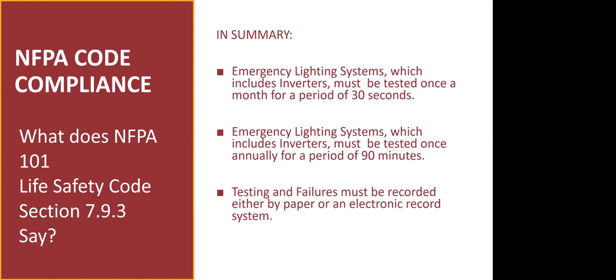That is the following. We're talking about the emergency fixtures in the space. We're talking about any wall controls that might be on the wall, or an aux sensor, any type of control that might be triggering those lights to go on and off. Any type of bypass devices that are used to bypass those controls, and then anything that is providing the power to that system. So in our case, the inverter would be considered part of the emergency lighting system.